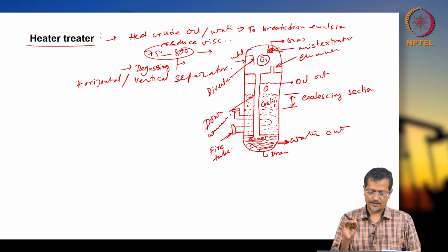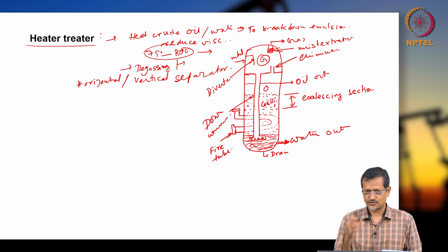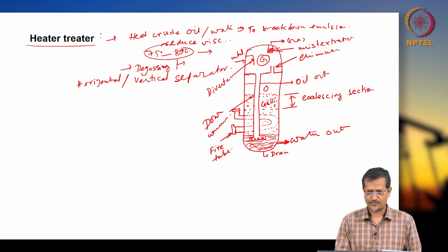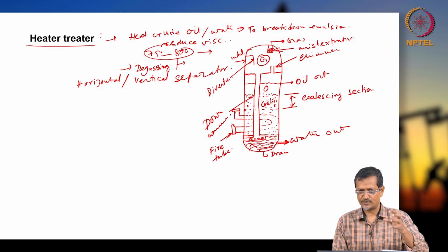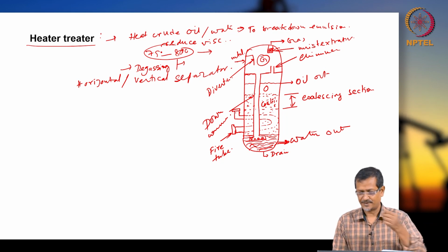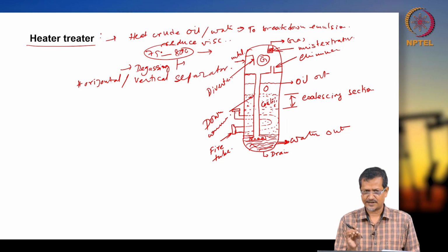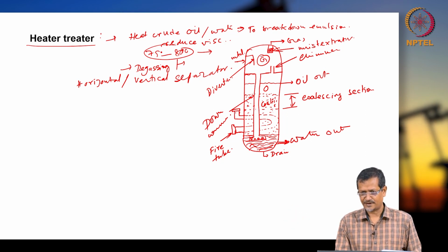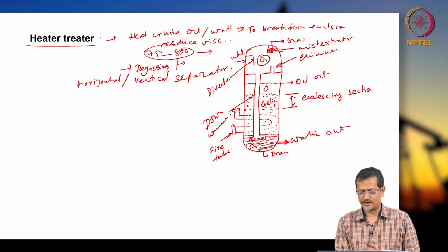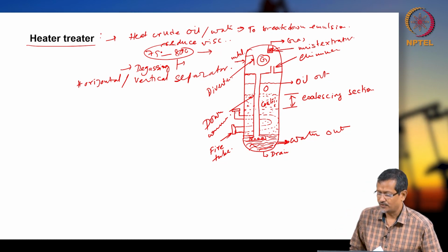Fuel gas means, like, a fire tube is there, and the fire tube needs some energy to heat, right? So to reduce that, the water heating time is reduced. If you are heating water for a longer time, it will take more heat, so the fuel needed to heat this system will be more. So to reduce fuel requirement, you give 3 to 5 minutes retention time and remove the water. Continuous inlet flow is coming in, and the water is retained for 3 to 5 minutes.